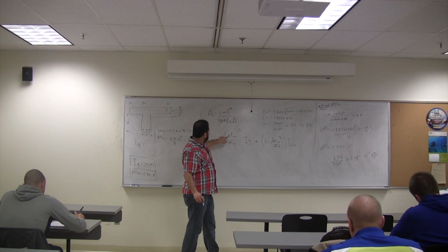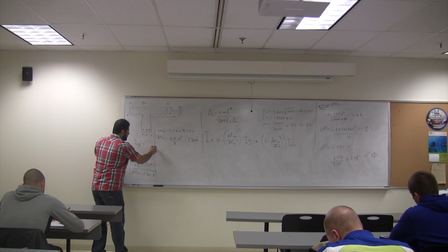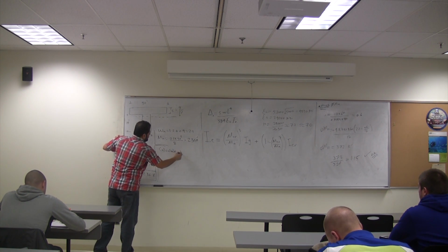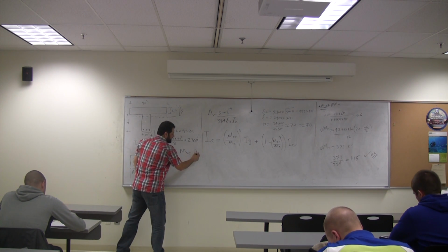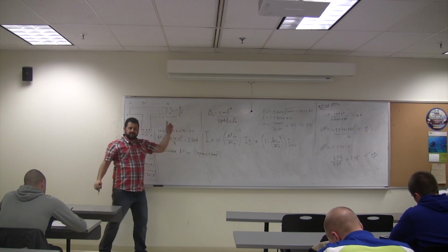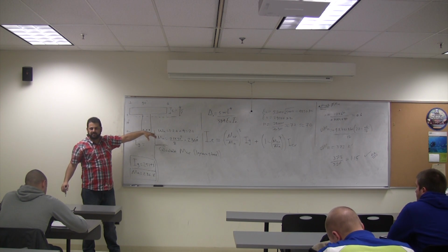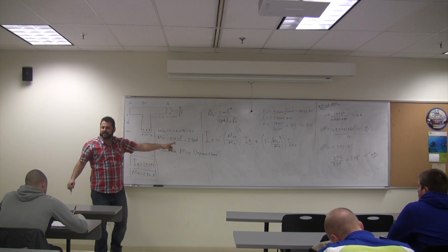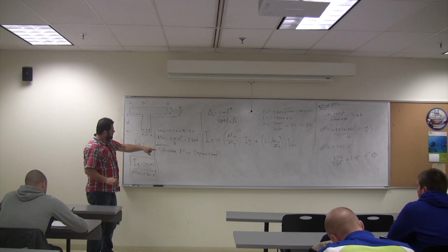We have this. Let's find M crack. Calculate M crack. I'm going to ignore steel. The only reason I'm ignoring steel is because it is a T-beam, so its effect is very small. In rectangular sections, you have to calculate what? I gross, I crack, transform. You know this, we covered it in detail. But let us do this one.